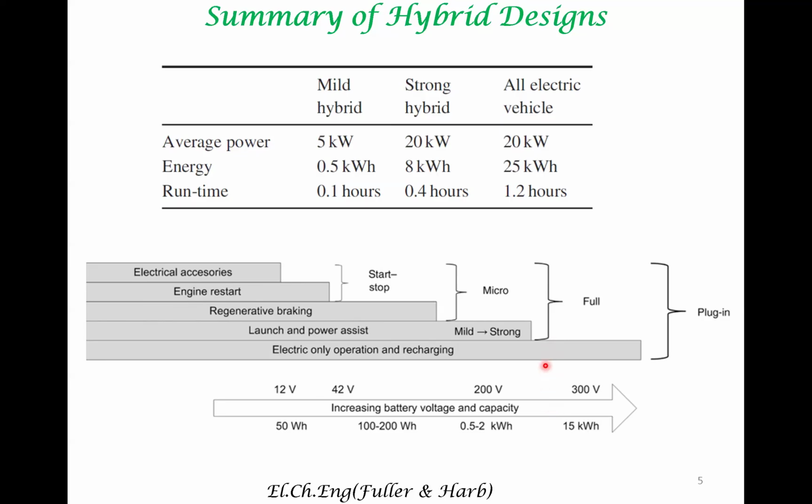In all these cases, the regenerative energy storage system cannot be recharged externally. If you can recharge externally, that kind of a hybrid system is called a plug-in hybrid. Okay, so in the nighttime you may just use an electrical socket to recharge the rechargeable energy storage system, which may comprise a battery as well as a capacitor. Such a provision to recharge the battery or the RESS is called a plug-in hybrid.